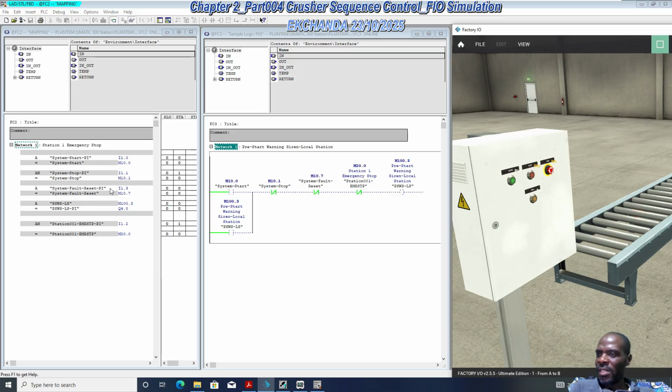It's not working the way it's supposed to work. In this case, as opposed to replacing the whole input module or output module, you can just simply reassign the input to another address or another location on another input module or output module which is not occupied, okay. This works to our benefit.